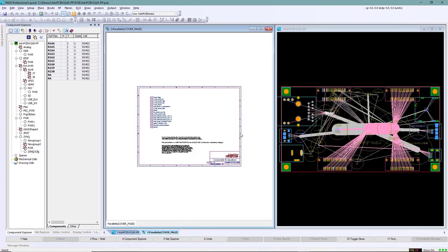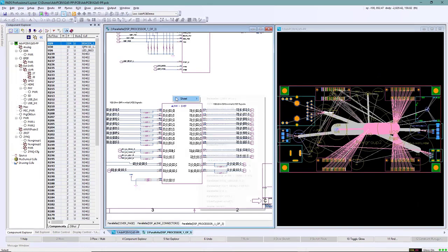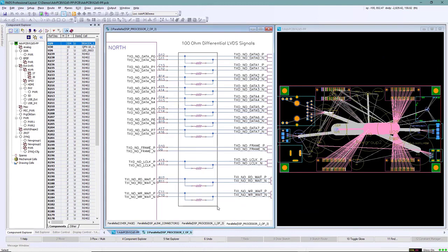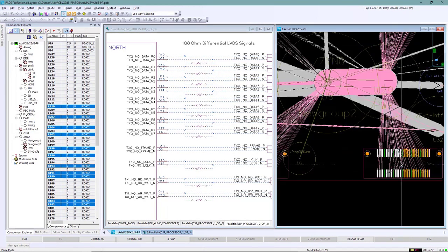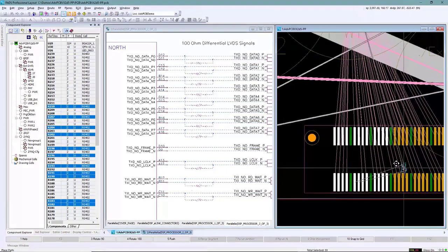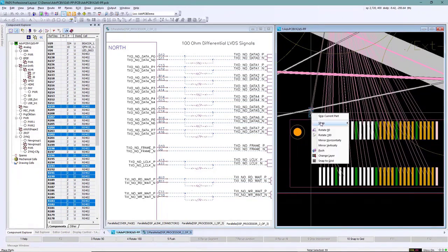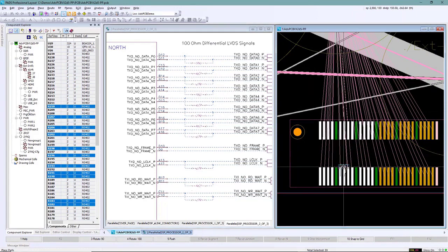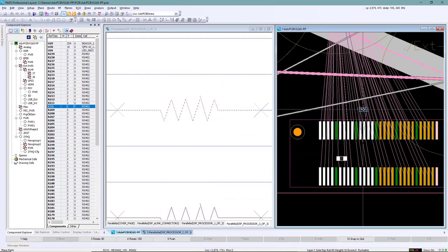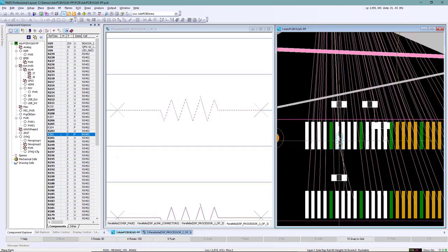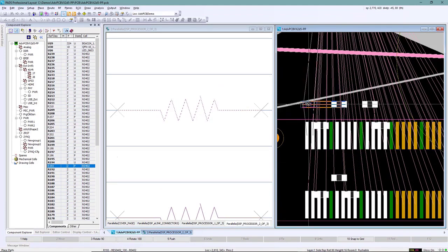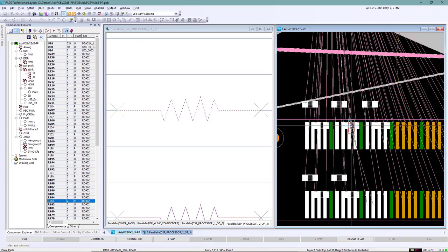Most every schematic and PCB tool can cross-probe, assisting with placement. However, to simplify this task, we can use an embedded schematic viewer with simplified controls. Passive components always pose a challenge to place with their large number in the design. Binding via the schematic using sequential placement makes it a snap. While placing a termination resistor for this connector, we'll use alignment technology to speed placement.